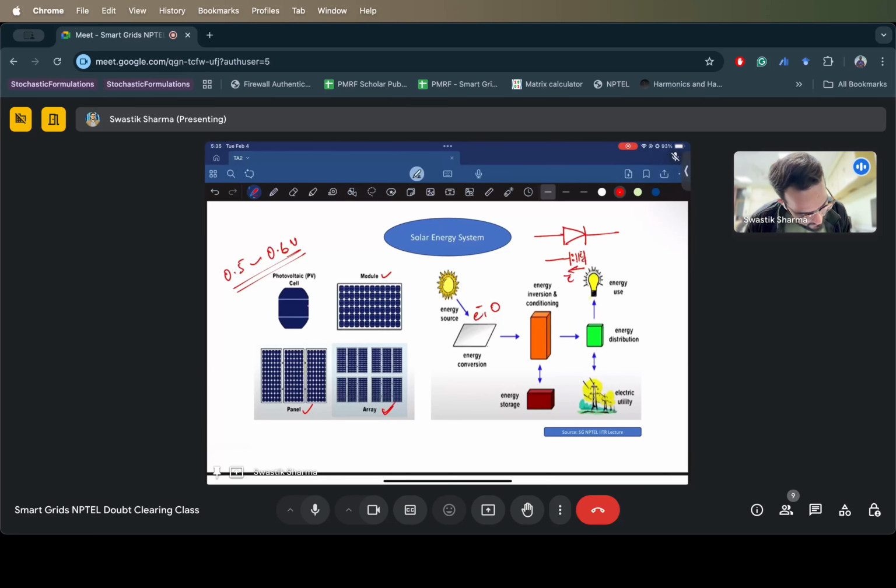Electrons start flowing over here, and there is a drift current which goes in the opposite direction. This is called drift current. So if we energize sufficient electron hole pairs, this drift current will surpass the potential barrier formed at the diode, and they jump it to form a regular current. But this current is DC, so we get a DC output from the solar cells.